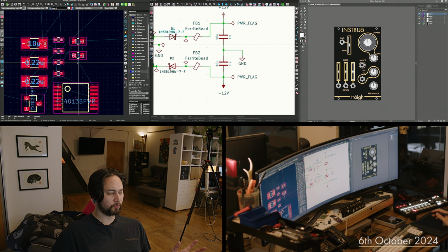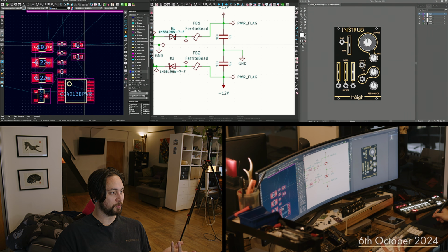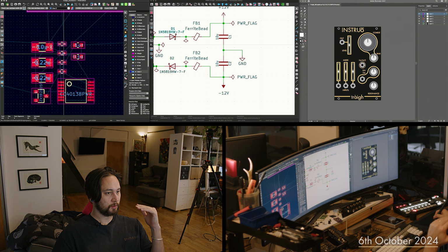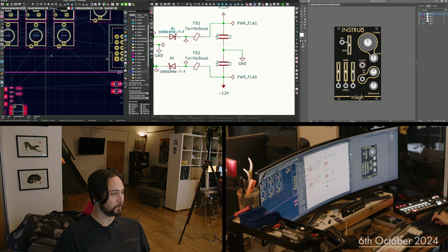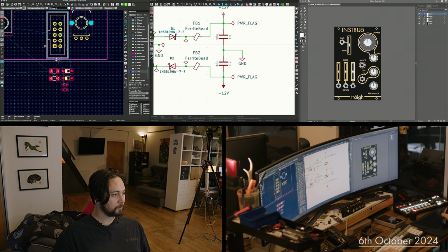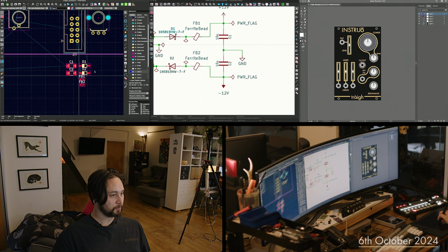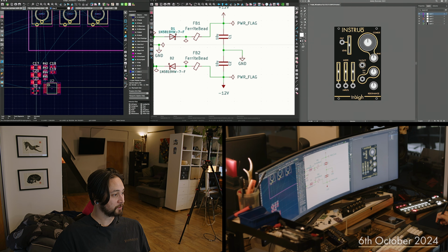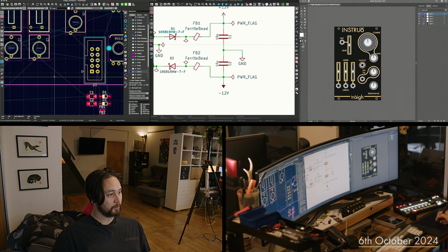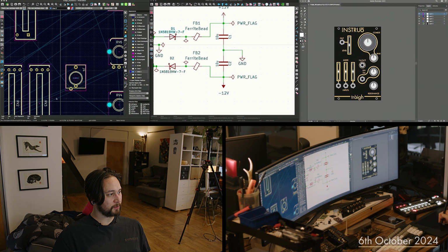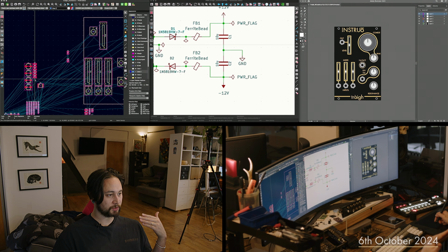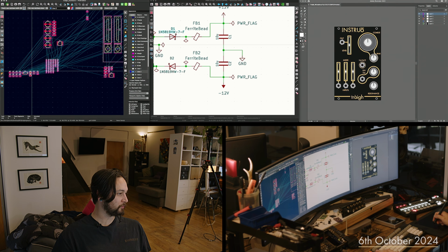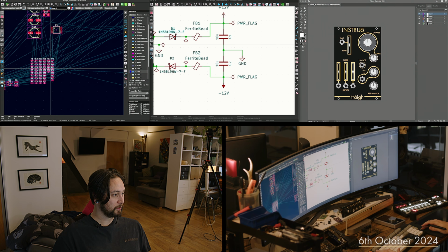It's kind of a rollover from how I did it in Eagle, where I would put the value or the designator bang in the middle. So if I'm printing off a map for doing hand assembly, all the parts are right on the origin. I found that clearer to work with. User 1 is designator, so they're slightly off. I placed them in positions that it would make sense if I was putting them on the silkscreen ledger, or I can export just a reference designator layer for the fab house, so they've got a reference point of where it is.